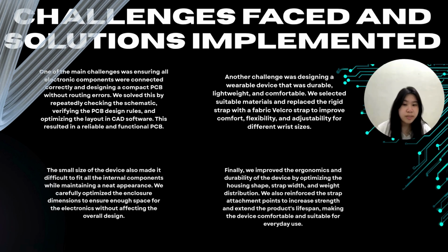Another challenge in the mechanical part was designing a wearable device that was durable, lightweight, and comfortable. So we selected suitable materials and replaced the rigid rubber strap with a fabric Velcro strap to improve comfort, flexibility, and adjustability for different wrist sizes.